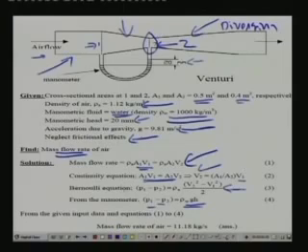So, if you use the input data and these 4 equations, you will find that the mass flow rate of air is equal to 11.18 kg per second. So, this is one very useful application of Bernoulli equation to a venturi meter. There are many other applications of Bernoulli equation. As I mentioned, it is one of the most useful equations, and you find its applications particularly in air conditioning or duct design and in refrigerant piping design, etc.